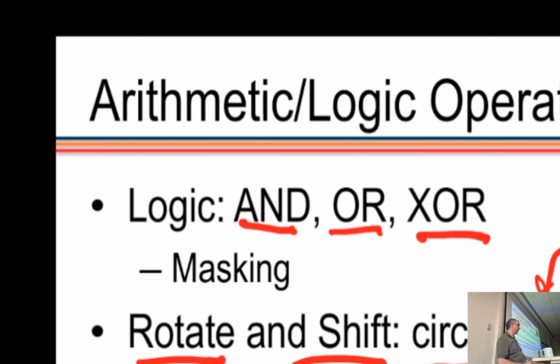But if it is arithmetic shift left, you read the first value from the right and insert that as a new value. So you repeat the value that is already there. In some other shift, you take this and put it on the right. It becomes rotate. And there is also rotate right, or the opposite direction. So rotate left, rotate right, arithmetic shift left, logical shift right, arithmetic shift left, logical shift left. So there are multiple types.